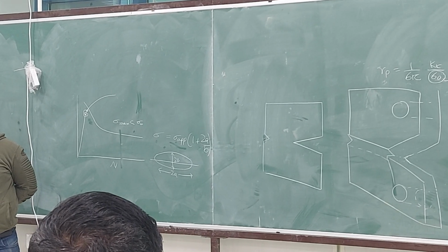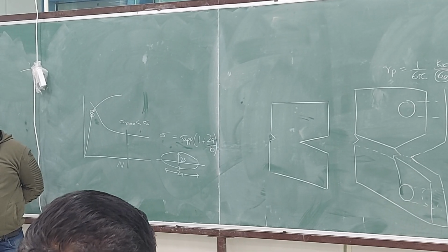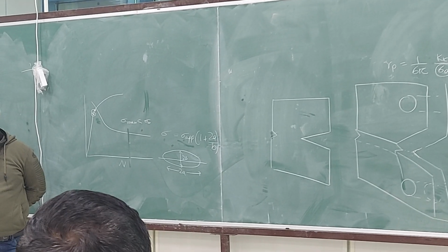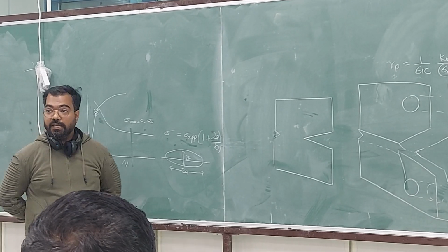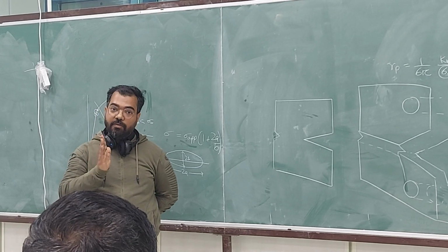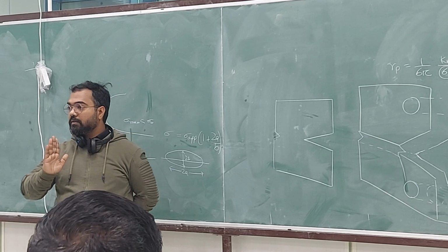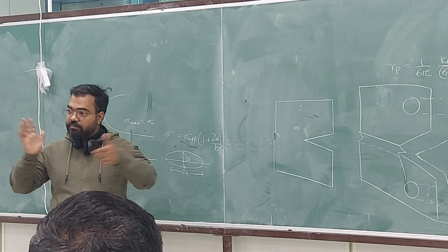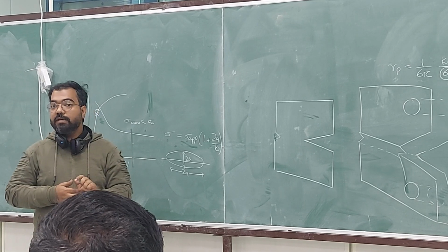At those numbers of cycles, when they looked at the microstructure, what they found was slip bands. What are slip bands? Slip bands are collections of slip lines. What are slip lines? Slip lines are the steps formed by dislocations when they reach the surface. You can't really see one slip line, you see accumulated slip lines.